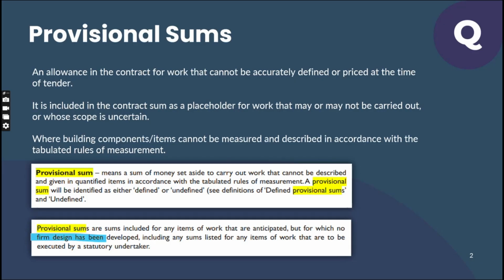And then, through nomination maybe, I will tell the contractor to enter into contract. So for the ID item, even though the full design is ready with you, you still call it a provisional item. You are not including it in the main contract. You call it a provisional item and you put almost the same amount in the provisional sum.